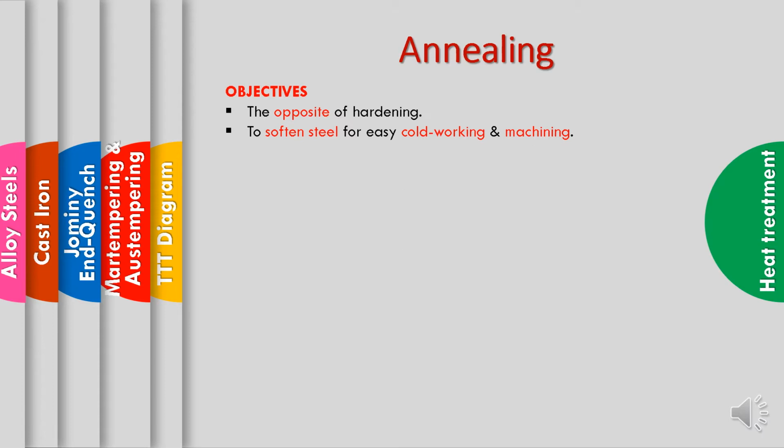So by annealing, we can soften the material for easy cold working and machining, and refine grain size to improve mechanical properties in terms of strength, ductility, and toughness.